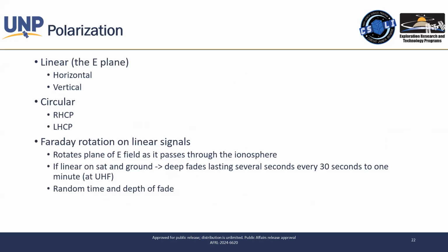Polarization. This is something that's also important. When we transmit through the electromagnetic field, we transmit with respect to some type of polarization. What that means is basically, when the wave is going a certain way, that electric wave is what we polarize against. So when that electric wave is going up and down, that's a certain type of polarization versus going side to side. Does that make sense?